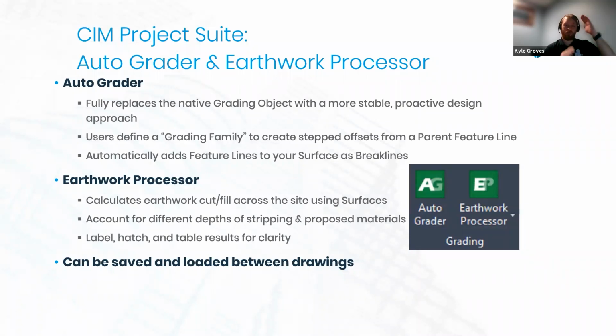It's a barrier type. It is 6 inches wide on the top back, and it's 12 inches wide from the gutter line to the flange of the curb. So that's a very common curb configuration scribed out by MnDOT. So we're going to want to use that over and over again. Well, we just load it into our drawing, make sure that our parent feature lines are being found, and press play. And that's how we're going to get all those child offsets.